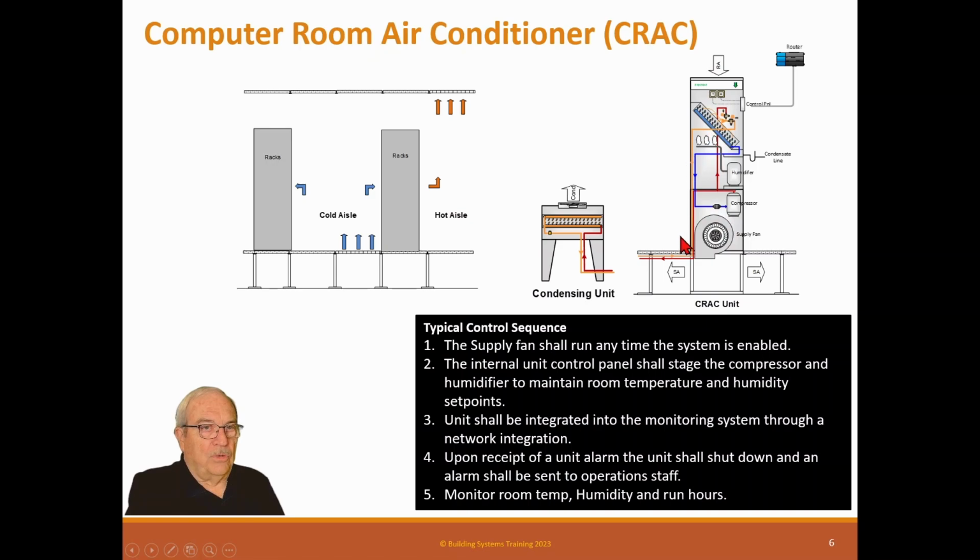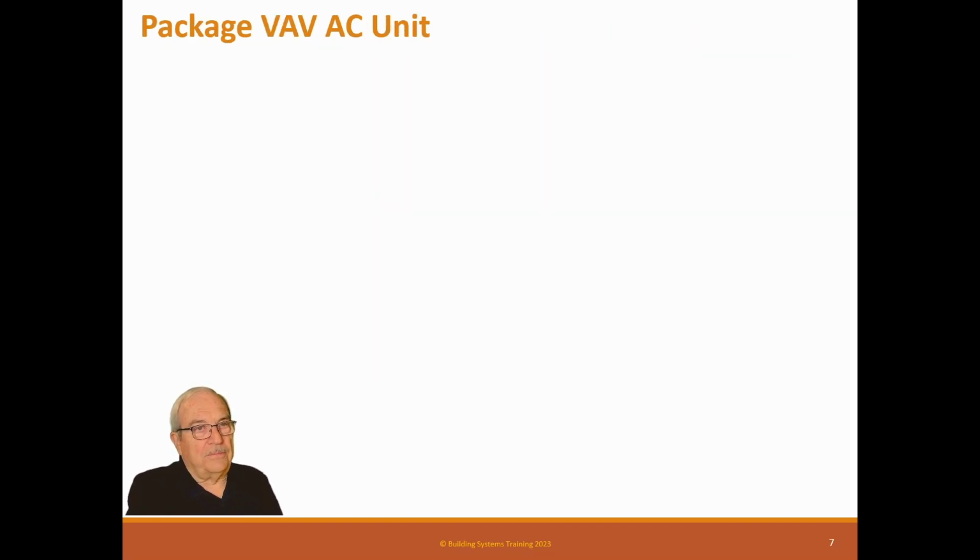The units are really good, really dependable, and really accurate on temperature and humidity. They're very good units, but the only problem area is the humidifier. Because the humidifier uses water. It's not the humidifier's fault, but water's corrosive, water's dirty, water has lots of components in it, and so the humidifier is a maintenance issue, and we have to keep an eye on those.